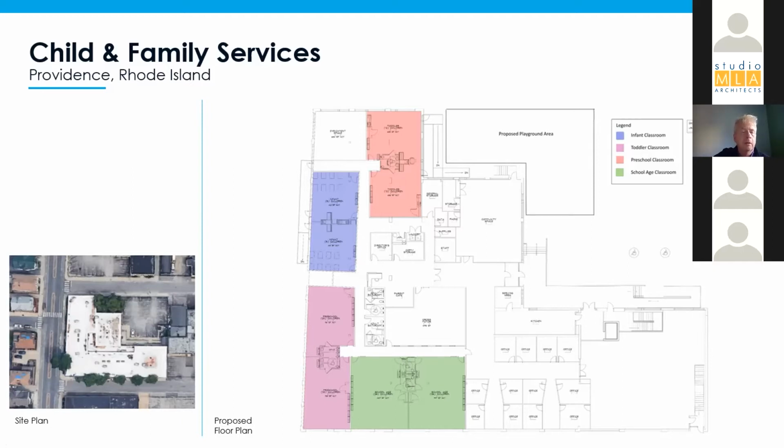The entire building is on the same level here, which is ideal, but it's all elevated from the street. And so openings for doors would need to be added to the exterior to allow egress directly from the classroom spaces. And unfortunately, multiple ramps would likely be required along the perimeter, which would be pretty difficult actually because the building's flush to the sidewalk on three sides, as you can see here on the site plan.